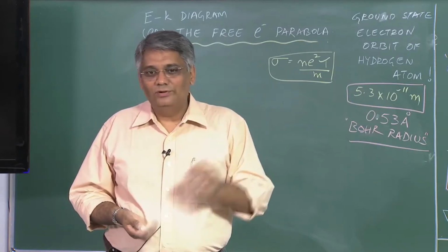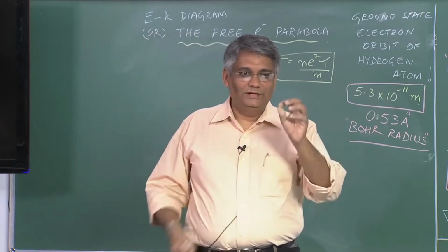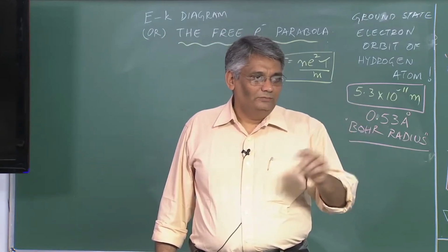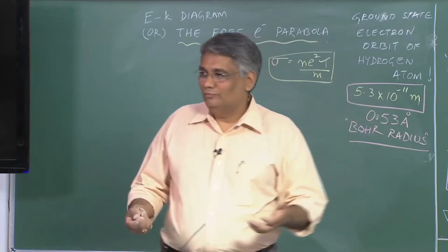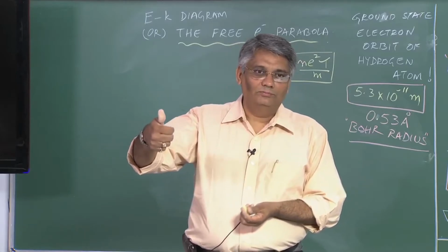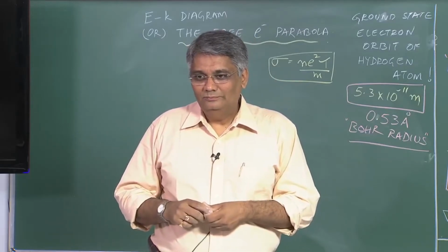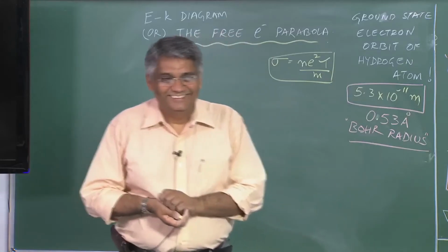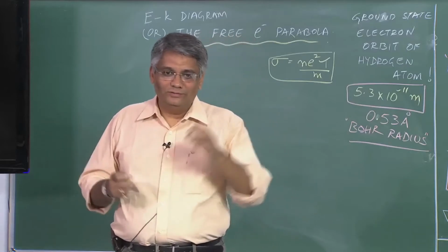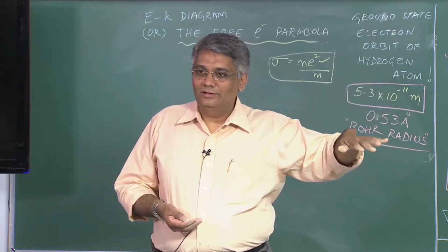So are these also free electrons like in good conductors? Because if I have a phosphorus atom replacing a silicon atom, phosphorus shares with 4 electrons of a silicon atom, and there is one excess electron coming from phosphorus, and that is free to move. Is that electron free to move? Is it a free electron? In that case, this electron should have the same property in terms of propagation in a lattice as the electron in a good conductor also.